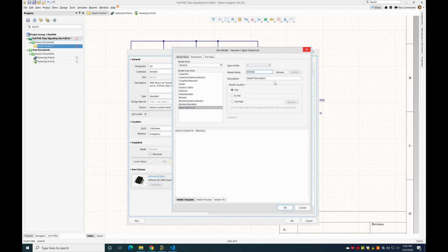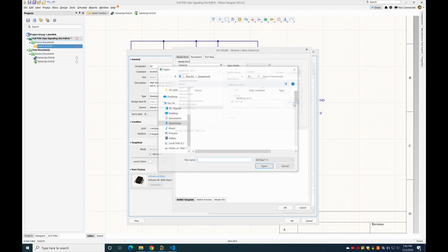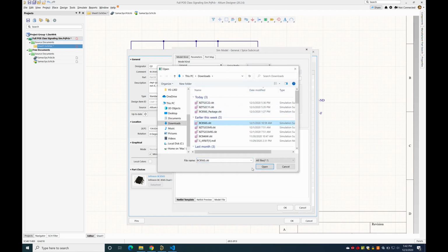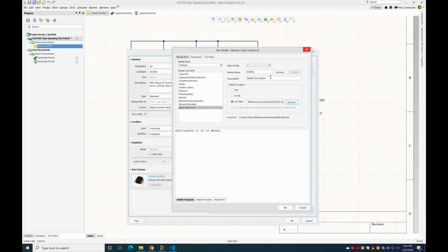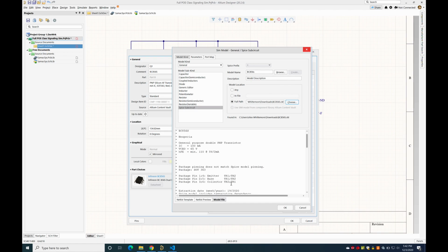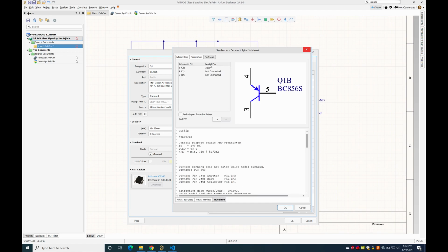I was trying to play with Altium 365 at the same time as I was doing this work, so I tried to make these components as 365 managed components. It turns out the managed component system doesn't really support port mapping for SPICE models at all. In this particular case, I couldn't get it to work properly, even by wrapping my 3-pin model in an additional subcircuit that expanded to the full 6 pins of the package. Regardless of what kind of gymnastics I tried, it just would not let me associate a simulation model with my managed component that actually worked out of the box.